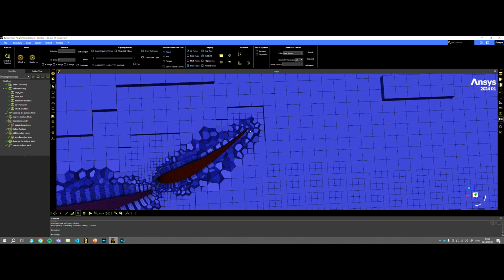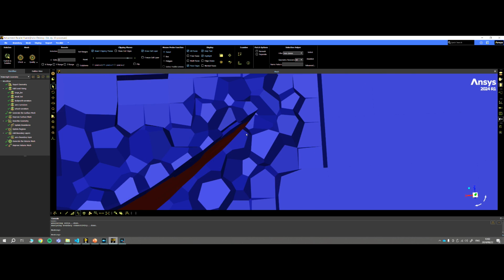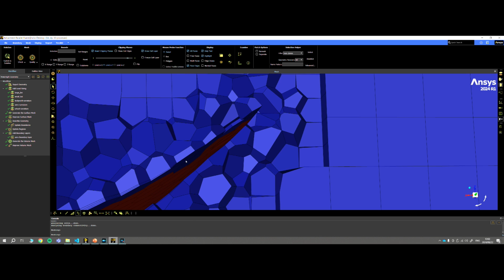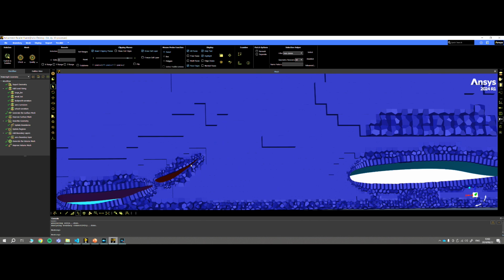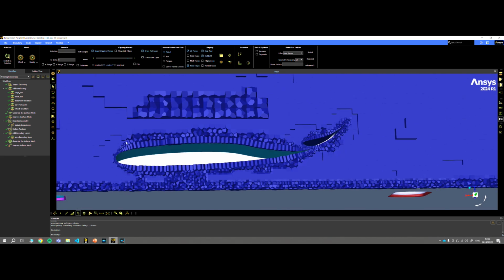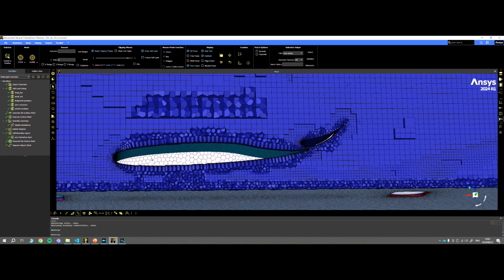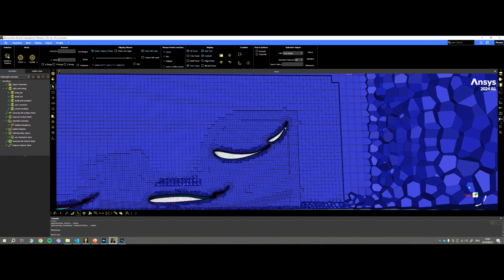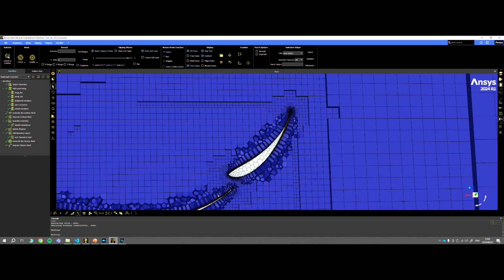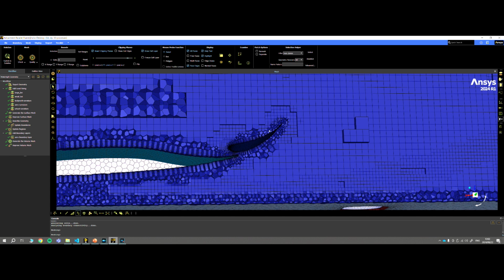The same thing can be seen on the second element of the front wing over there. The stair stepping is also likely due to the large element sizes used, given the global multiplier was set as 3 for this demonstration. So setting it to 1 should also correct that issue.